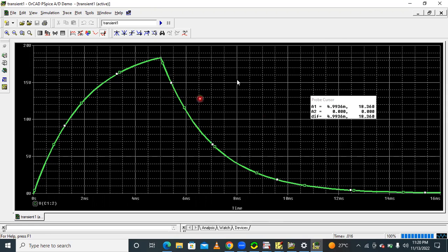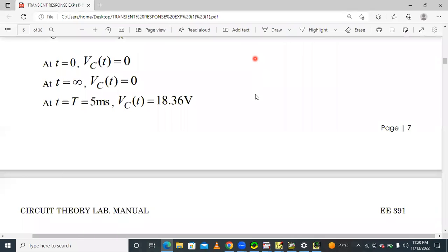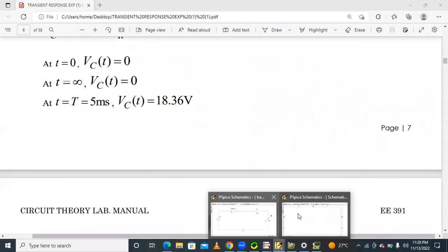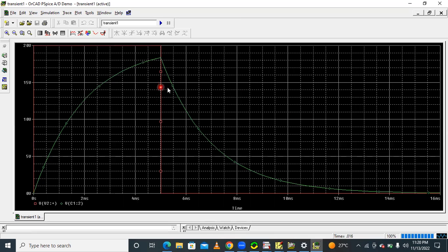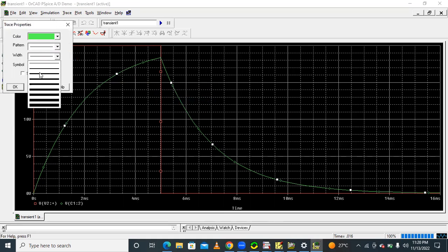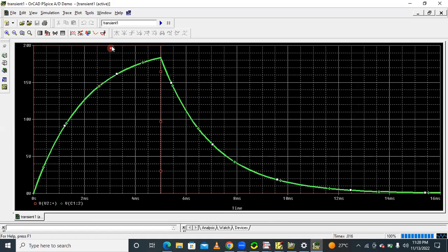By connecting one voltage marker at the source as well, both will be displayed simultaneously like this. Then run, and enable the properties; the width of the pulse signal changes like this, and the red color is our input.